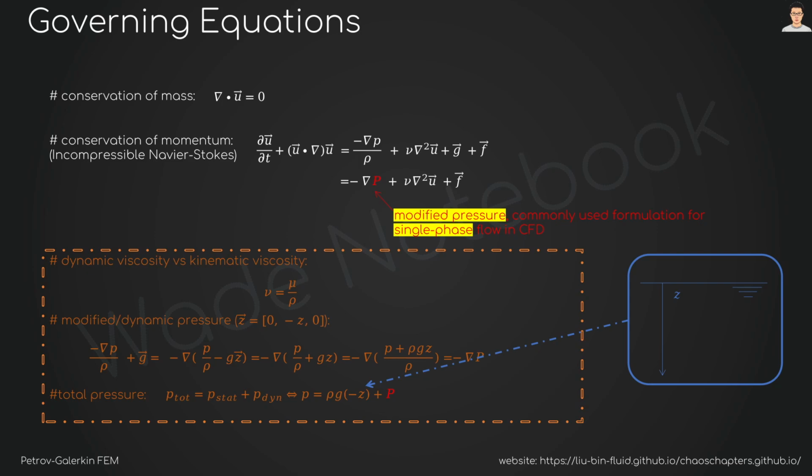Now, if you get a chance to successfully formulate the variational form of incompressible flow once, you will realize that the finite element terms associated with the time derivative and advection terms are usually straightforward.